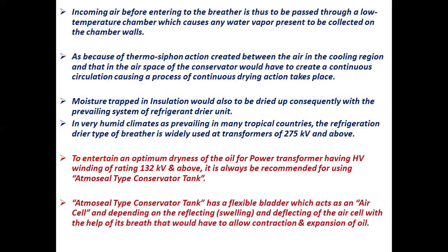Moisture trapped in the insulation would also be dried consequently with the prevailing refrigerant dryer unit system. In very humid climates, as prevailing in many tropical countries, the refrigeration dryer type of breather is widely used on transformers of 275 kV and above.